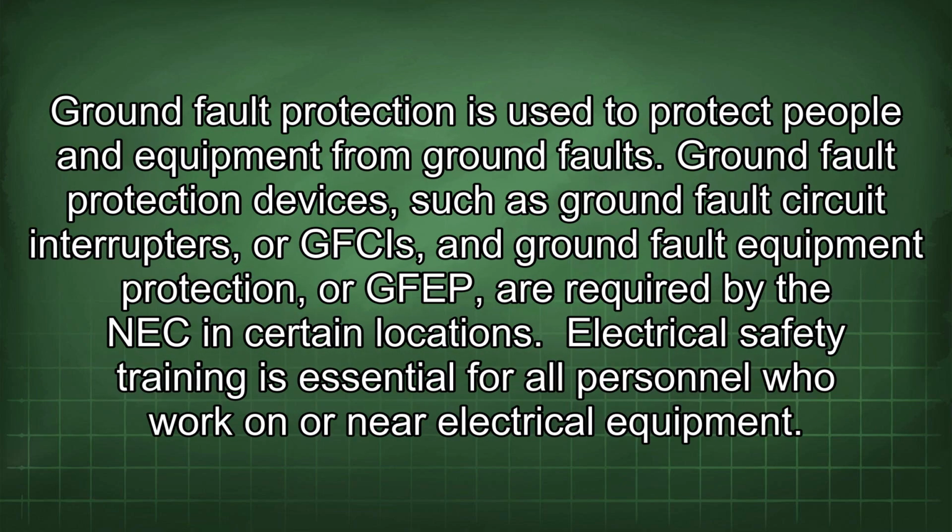Ground fault protection is used to protect people and equipment from ground faults. Ground fault protection devices, such as ground fault circuit interrupters, or GFCIs, and ground fault equipment protection, or GFEP, are required by the NEC in certain locations.